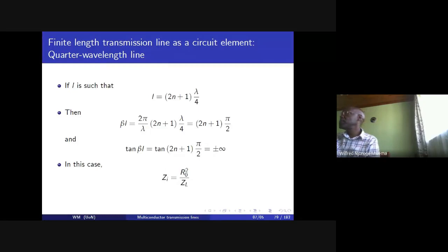This matters especially for those of us who want to use a single music amplifier in the house, and then run a very long line to connect our 4 ohm speakers to the amplifier. There are certain frequencies for which the amplifier will be seeing no load, that is, open-circuited, so the speaker does not appear, or the speaker is short-circuited. And those frequencies will be shorted out. It's more like a filter, so to speak.